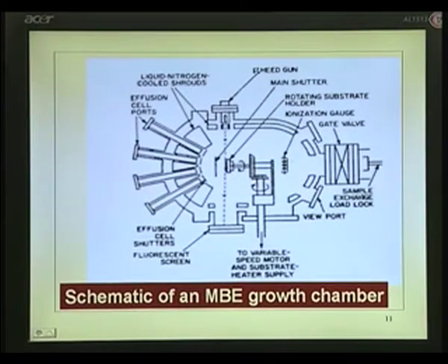There is a small mini chamber here, very small chamber. So, this gate will be closed when the run is made. You open this gate, insert the wafer into this portion through a wafer holder etc., keep it there, close the chamber, pump this down. This is a small chamber, otherwise that whole thing is a big chamber. So, you have a small chamber here which can be pumped down rather easily, maybe in an hour.